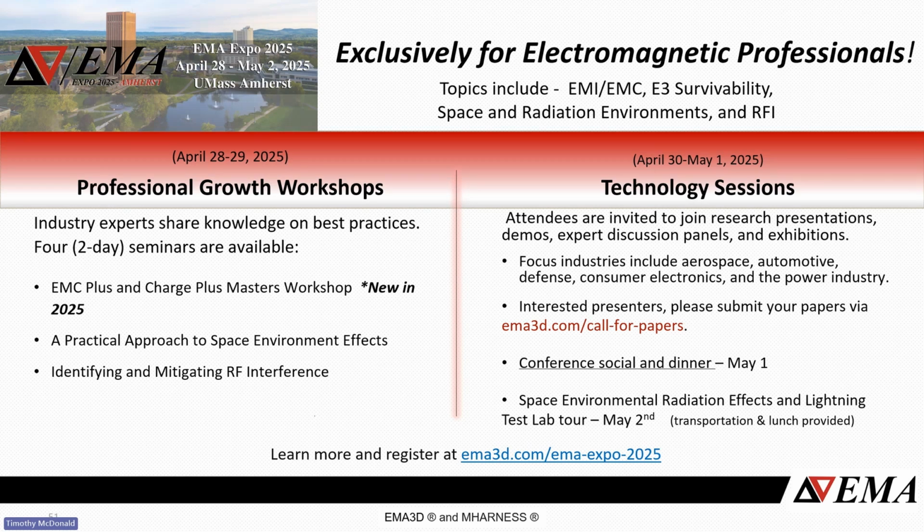Absolutely. So that's common work that people do at the vehicle level, looking at lightning and EMP attachment to a vehicle or illumination of a vehicle, as well as often we design the equipment with a CS116, CS117, or a DO160 section 20 or 22 test that flows those levels to the equipment. So we do have the ability to do that.